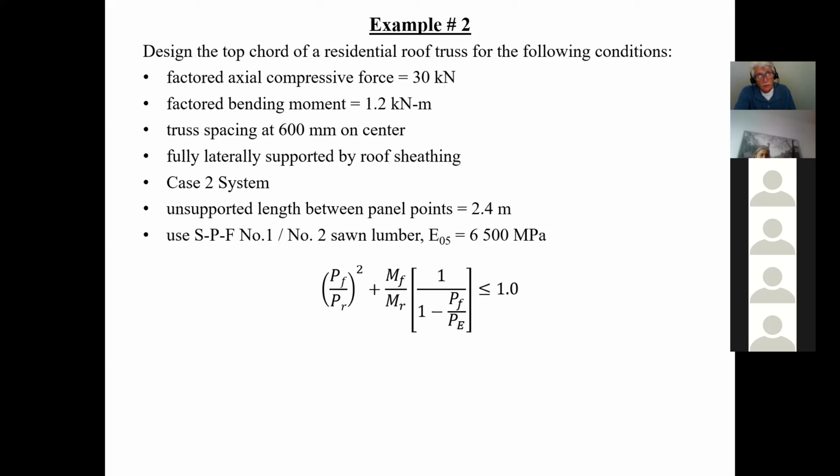it's not temperature change that really affects the truss. It's moisture change. Okay, not temperature, moisture. And I can tell you that, anyways, we'll talk about that for sure. I mean, there is temperature, but the real culprit with wood when there are problems with the truss is the moisture change, not the temperature change. And then I'll explain to you what happens in that case.